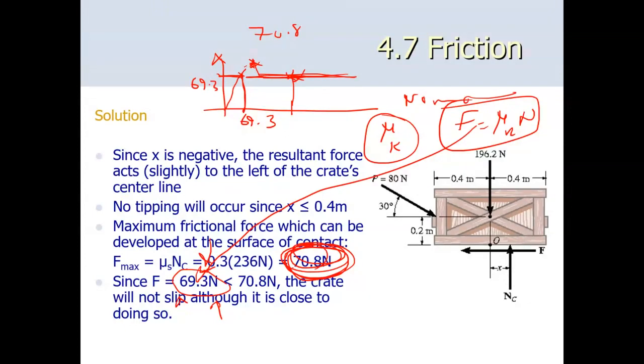So in energy and motion, with the friction, everything was lumped into a particle. This particle doesn't have any dimension. So whether it be W, N, or friction, everything is lumped at one single point. Here, the forces are distributed. You have a weight acting at the center of gravity. Normal force does not pass through the center of gravity. Friction doesn't pass through here, and driving force doesn't pass through here, generally speaking. So can you see the difference?